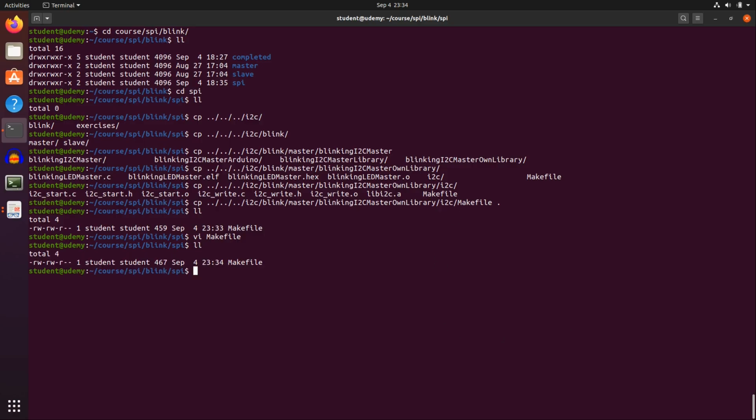So here I'm going to have a SPI master and SPI slave, and there are probably variables that I have to use across the master and the slave. So what I'm going to do is I'm going to implement a header file which has only hash defines inside, so they can define the ports properly.